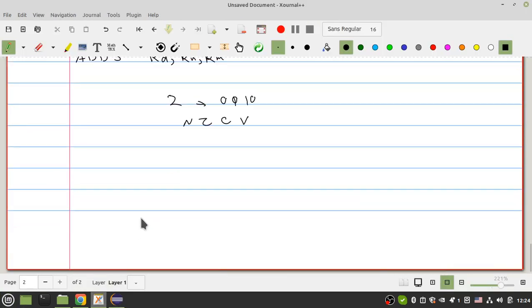For practice, you can study the ADC, add with carry, instruction, and with this instruction and other instructions you can write code that multiplies the value of, for example, R2 by R1 and puts the value in, for example, R5 and R4, because if you multiply two 32-bit numbers, the result is 64-bit, and you need two registers to save the result.